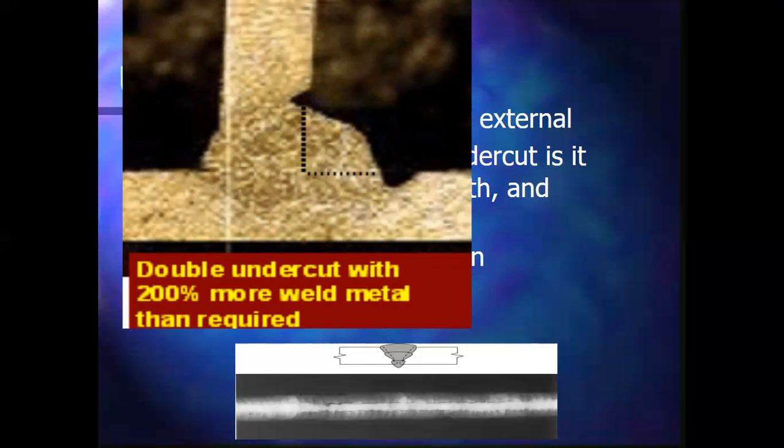Couple corrective things we could do is, if we're allowed to, put a weld in here, fill that in, put a weld pass right there to fill that in. That is, if it's allowable. Yes, Philip. Yes, you can. So that's how we'd address those.